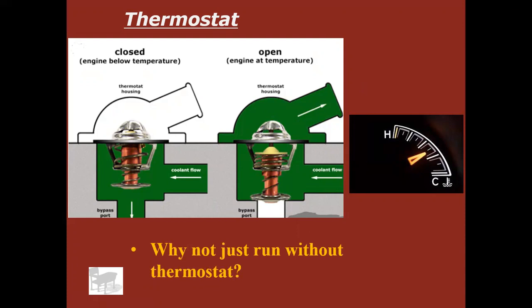I always like to ask, why don't we just run without a thermostat then? Wouldn't it be smarter to just rip that thing out of there and have full flow to the radiator so we can keep our engine as cool as possible? The answer is no, because you don't want an engine that runs as cool as possible. You want an engine that runs at the correct temperature.